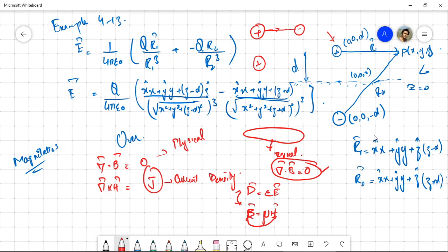ferromagnetic materials, and we will be talking about ferromagnetic materials much more than the other materials, because they are a certain kind of material that we need in different kinds of machines. In those materials, the value of B is not linearly linked with the value of H, and the reason is that the material goes into saturation, and at that point the linear relationship deviates. So this was the difference between these two things.